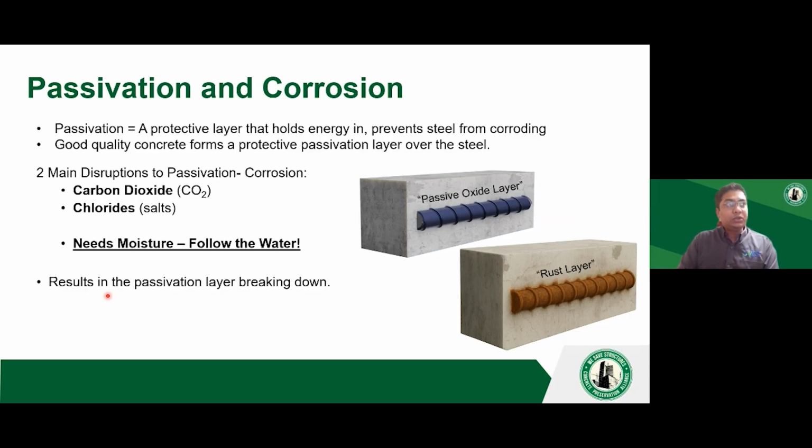This is not exclusive, like an exhaustive list. There are so many other species that can cause corrosion or depassivation, but the key culprits in concrete parking structures is essentially carbon dioxide and chlorides. Typically, these two species need water for diffusion, as I said. So a good rule of thumb is follow the water and you will probably see an issue with your concrete, or you'll see corrosion issues in your concrete. So follow the water.